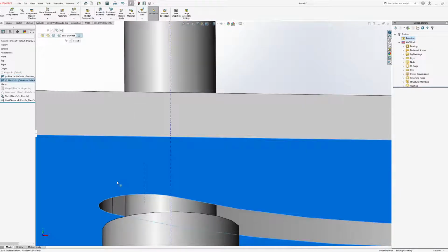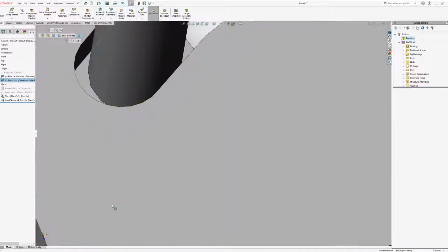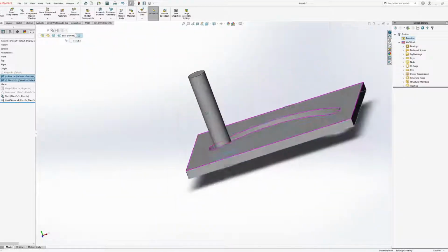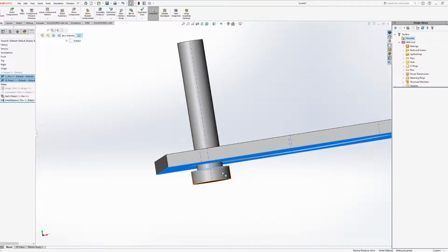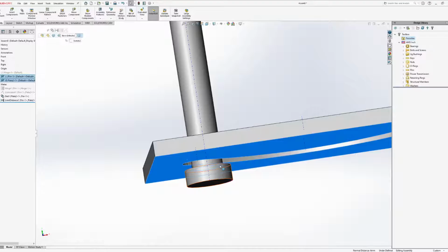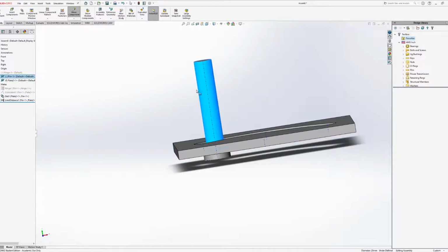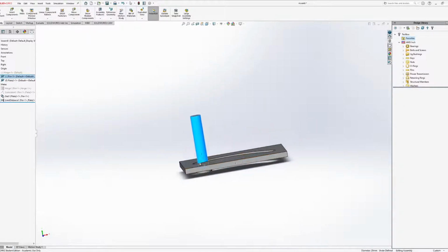And if I click here, and if I click there, we can see at the bottom it says a normal distance of 4 millimeters. So it's only allowed to go away from those reference points. It's only allowed to have a gap of that much between the two, but it can be butted up right against it.